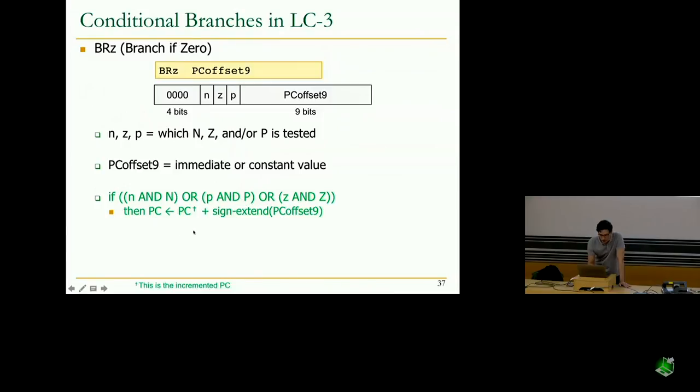If this condition is positively resolved, then we will store the result of this PC relative addressing into the PC. Otherwise, the value of the PC is not modified, and it is the incremented PC.